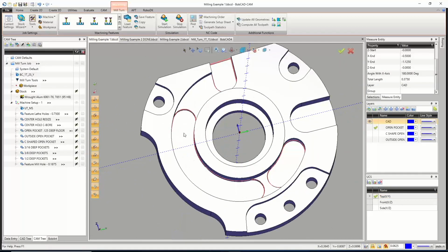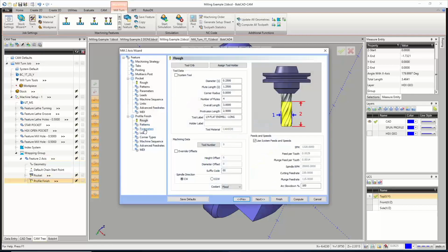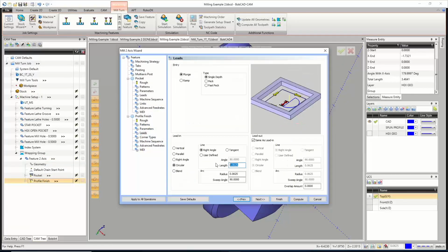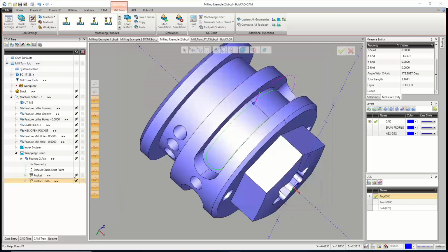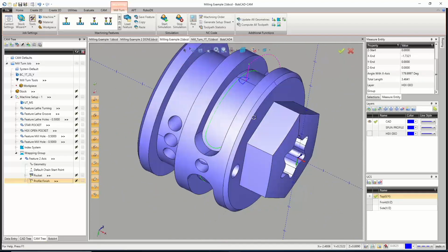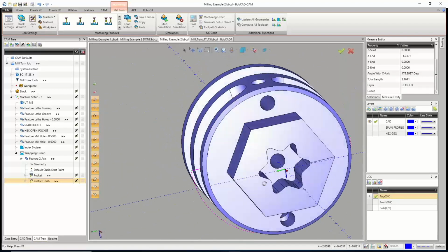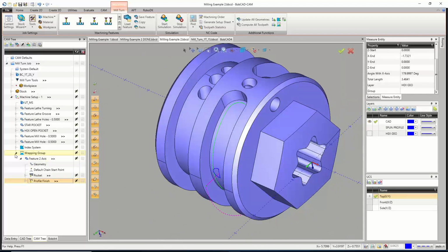No, totally lying. The groove that I couldn't fit the bigger lead in was this one, not the one we're using now. So I could totally go back into my finish pass here, edit this, leads. I mean, honestly, I think a 1/4 inch would fit. Let's find out. 1/4 inch lead fits just fine. So yeah, wrong groove. Other than that, that should be everything.